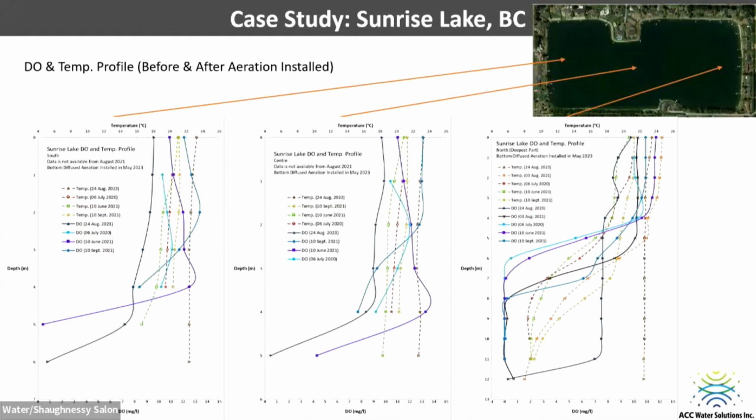We have the technology now where, yeah, it's expensive to go out and do water chemistry every single week on a water body. We now have sensors we can put in for a relatively low cost that will give you real-time monitoring data that allow you to make more informed decisions. There are cases, for example, small stormwater bodies, where the monitoring doesn't make a lot of sense.